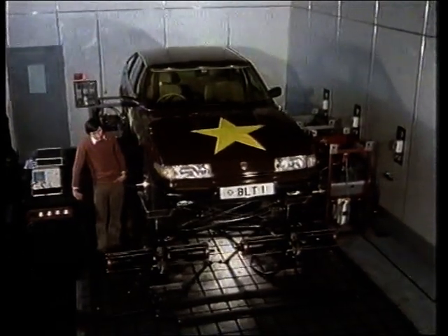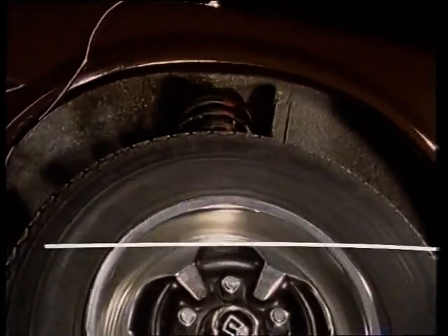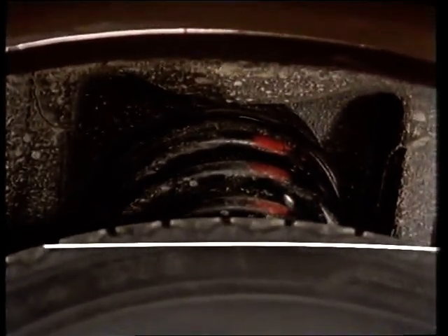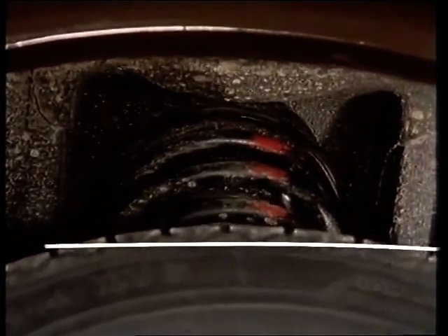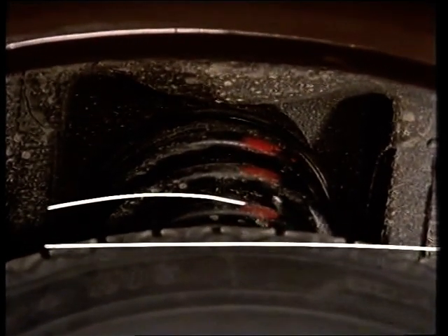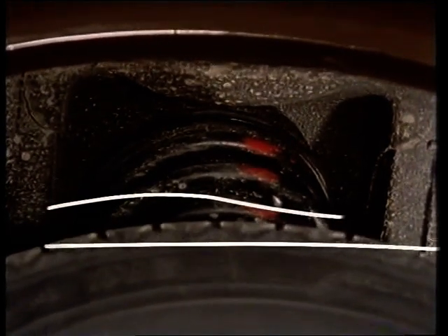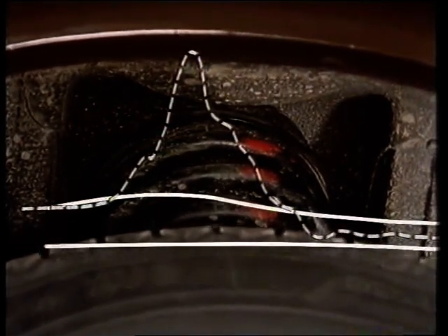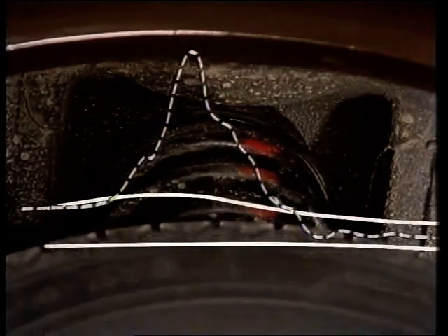So how about the damped car? As before, we'll increase the input frequency at constant amplitude. And you can see what the transmissibility curve looks like in this case. Well, as you can see, the transmissibility curve is much less peaked than that of the lightly damped car. Well, I hope that's given you some insight into the nature of vibrations. We've looked at some of the characteristics of undamped and damped vibrations.